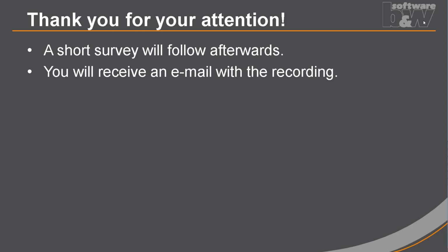For this to be possible, you first need to remove it from the references, or change it in the references before, which are usually the relations. So for this case, you need to create a relation check which renames your previous relation to the new name of the parameter, and afterwards also rename the parameter. This way you can rename parameters easily.